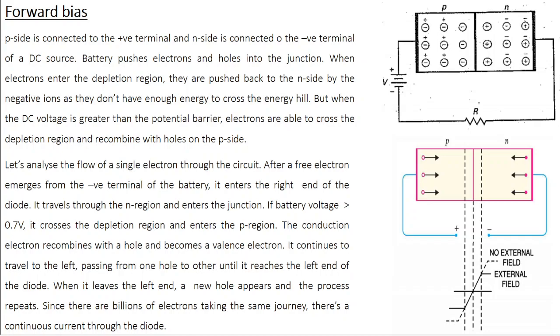But if you increase the bias slightly higher, you make it 0.8 volt. Now what happens? Your forward bias voltage is higher than the barrier potential, so your applied force is greater than the resistive force. Here your barrier potential is completely overcome by the applied voltage. As a result, the free charges on either side are able to cross the PN junction. In other words, a tiny current is set up across the PN junction. When you increase the biasing voltage further and further, the value of the current is going to increase proportionally.